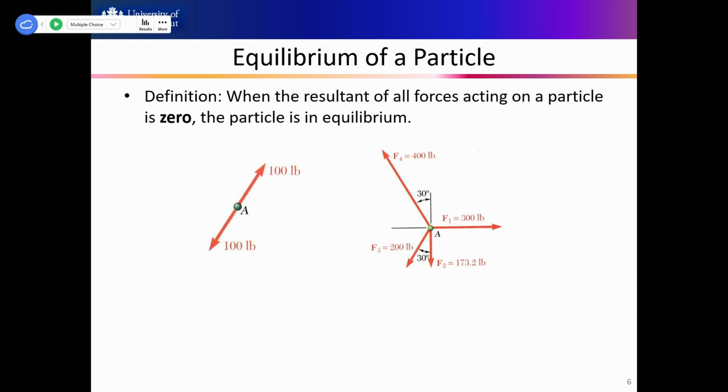It is tricky to say whether it is equilibrium or not because there are four forces. So in this case, we must use the equations. This vector equation: the resultant vector is the sum of all the forces, so the vector sum of all the forces equals zero. And in 2D, we have x and y directions, so we can use these two equations. The sum of the x components of all the forces is zero, and the sum of all the y components of the forces equals zero, then equilibrium. Yep. So these two are called equilibrium equations.